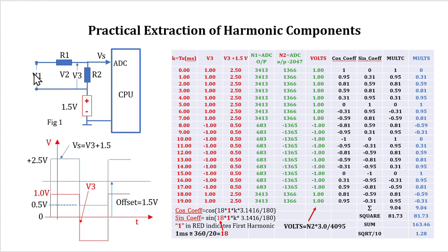Then we cannot apply any value we want to the ADC. There is an upper limit on the value, and also we must ensure that we always apply a positive voltage. So first you attenuate it to an acceptable value.